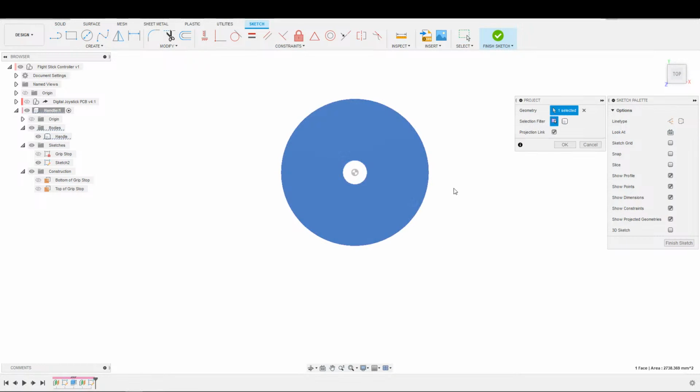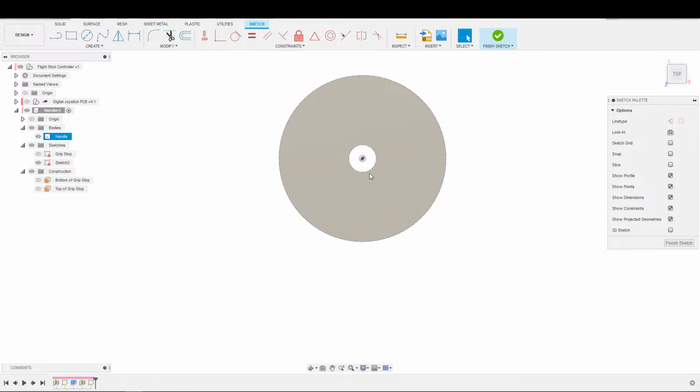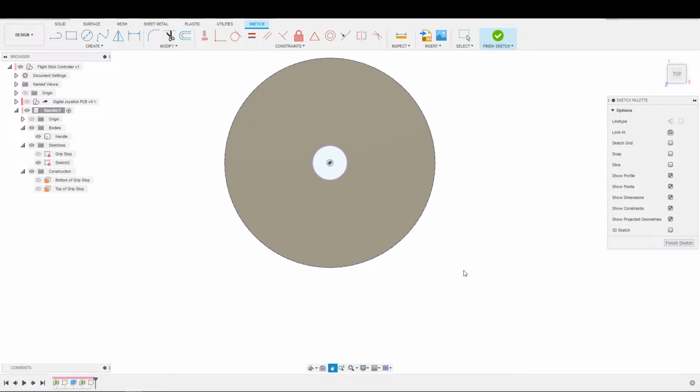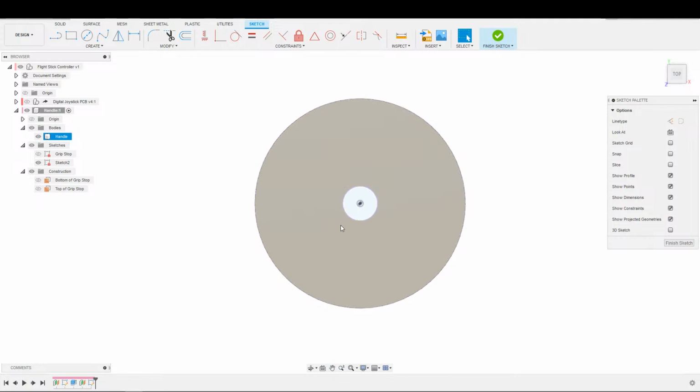Project this out. Actually, keep that there. So we said we had 8 millimeters before the threads, or 8 millimeters of thread, about 8 millimeters of thread. Let's see. We are 4 up. We did 15, so we're at 11. So we need to go 3 millimeters up, right? 15 minus 4 is 11, minus 8 is 3. Okay, good. Math on stream. So let us go ahead and get that taken care of. Well, do we want to?